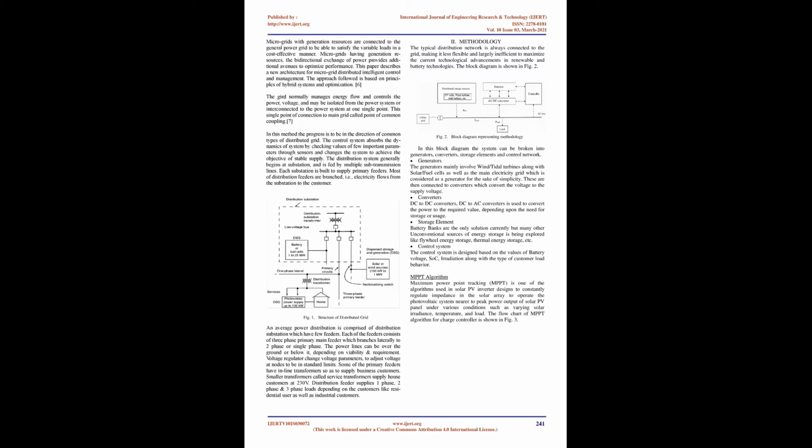Lyapunov function-related decentralized control mechanism for a single-phase parallel-connected inverters system within an island microgrid. In this paper, voltage regulation, like amplitude and waveform, and power/current sharing is assured even in the presence of unknown line impedance and unbalanced LC filter parameters. Higher reliability and robustness are ensured since no intercommunication between inverters and no centralized controller is implemented, which also gives the advantages of scalability and redundancy.